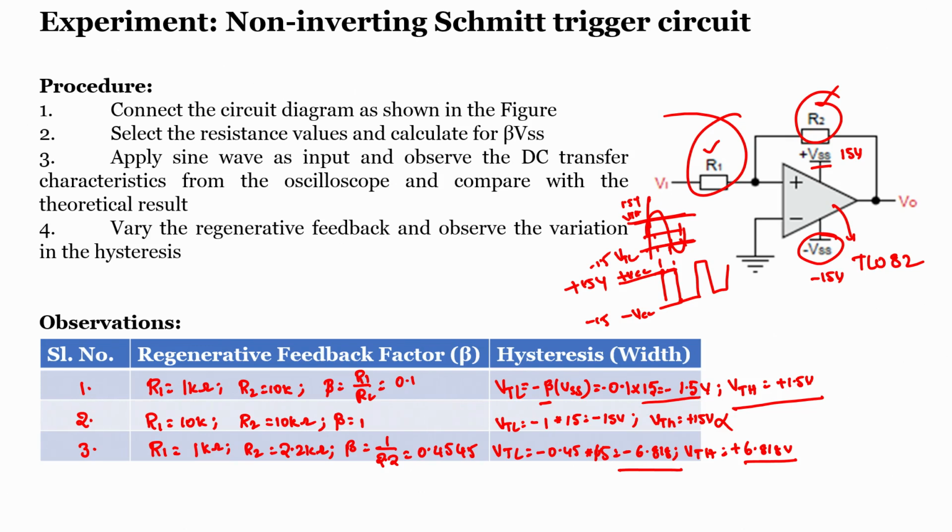If I want to design using a comparator, it is not possible. With a comparator I can only put one threshold, either at 50 or at 70. If it is a comparator and I set it at 70, when the input temperature is lower than 70 it will switch on, and if it is greater than 70, it will switch off. But in this case it is not like that. When the temperature is lower than 50 degrees, the heater will switch on, and when the temperature is greater than 70, the heater switches off.